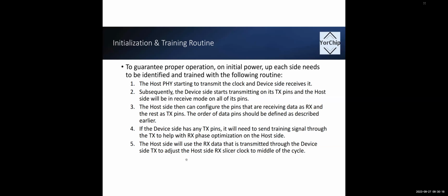When I think about it, honestly, I wrote this, but some of it is completely unnecessary, because a lot of these things are the way we did things in the links, where we didn't really have control over both sides. In reality, when you're doing a chiplet, you're not going to change them. You can technically register select them in the beginning. So there's a philosophical argument that some of these pin orders can be register selected before the link even comes up. So some of it is unnecessary, and there's an argument to be had.